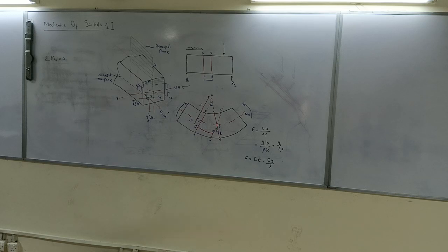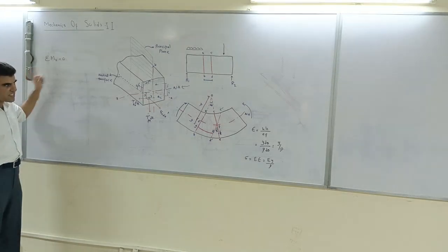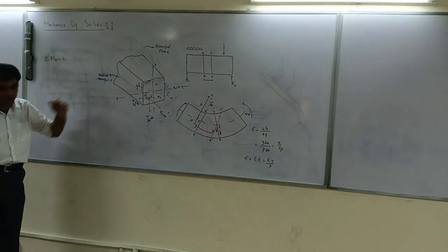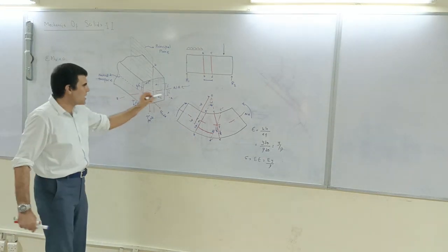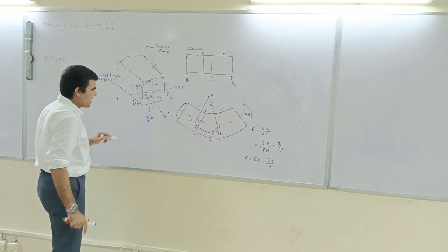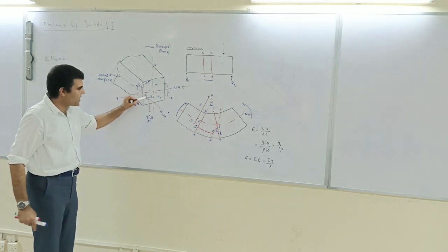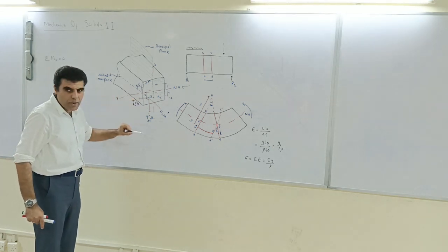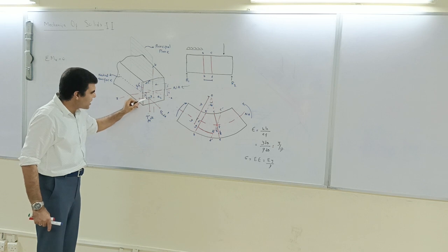So in this case we have that 0. There is no torsional moment. So therefore summation of Mx, that is 0 in this case. There is no twisting moment. So that will be equated to 0. And what is the internal moment? Internal moment is tau yx dA into z.